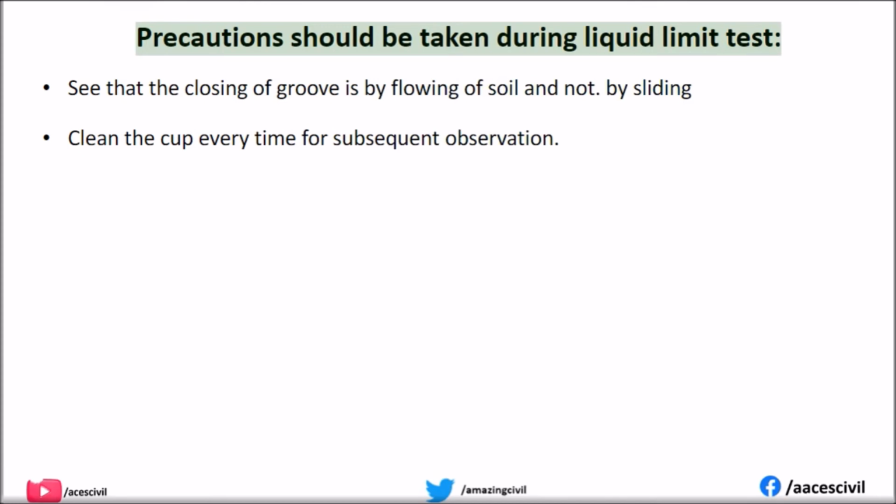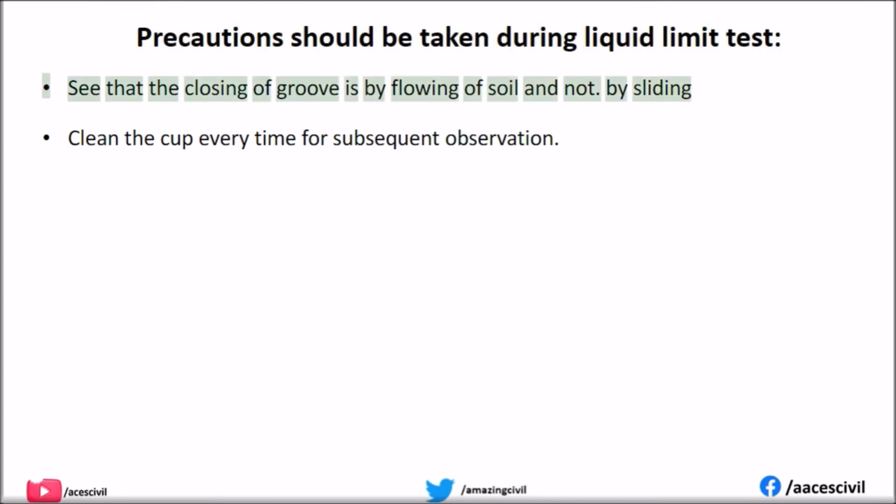Precautions to be taken during liquid limit test. See that the closing of the groove is by flowing of soil and not by sliding. Clean the cup every time for subsequent observation.